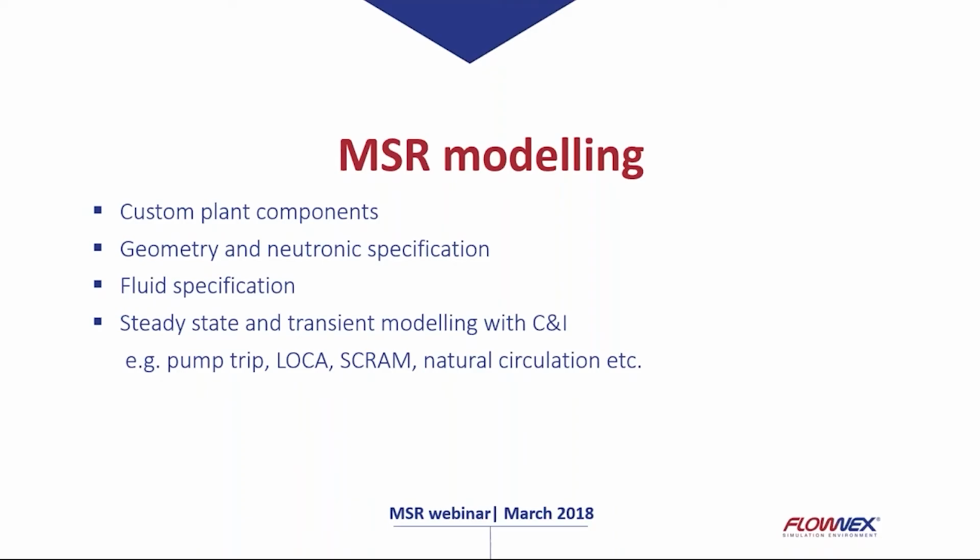Again, Flownex is used to see what will happen on system level, for example, with a pump trip, with a loss of coolant accident, with your control rods being fully inserted, natural circulation that will take place during no flow conditions and all of that. So that is what we are excited about with Flownex, and where we feel that we can add a lot to the market out there.